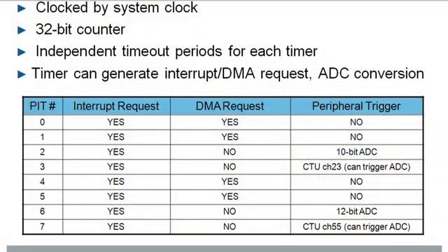We'll have a certain number of DMA channels, and each channel you will configure to describe what you're transferring from a source to a destination, how much, and how it does it, etc. And then you have options, after doing that so many times, to generate another interrupt request. So there's no CPU involved in a DMA request, and that's a nice thing about it. So you can avoid interrupts by using DMA. So the PITs can do this, generate a DMA request after a timeout.